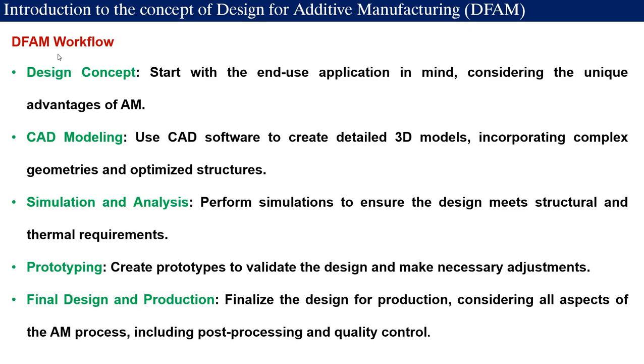Then how does this DFAM workflow go? It is just similar to the steps that we discussed in unit number 1. We have the design concept. We have to start with the end use application in mind, considering the unique advantages of AM. So first is the idea. Second is CAD modeling. Using any CAD software, you have to create detailed 3D models incorporating complex geometries and optimized structures.